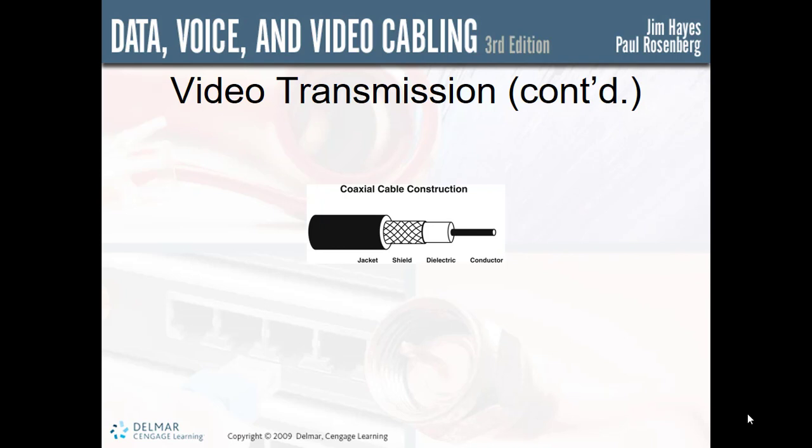In addition, the outer conductor acts to contain the signal inside the cable, reducing the emissions from the cable that cause interference in other electronics and the interference of other outside sources on the signal in the cable itself. The signal in coax cable is a simple voltage. It can be introduced into the cable at either end or even in the middle, where it will be carried by either end. In any application, it's important that the transmitters be selected to be appropriate to the characteristics of the coax cable. And both ends must be terminated to prevent reflections that could then cause interference.